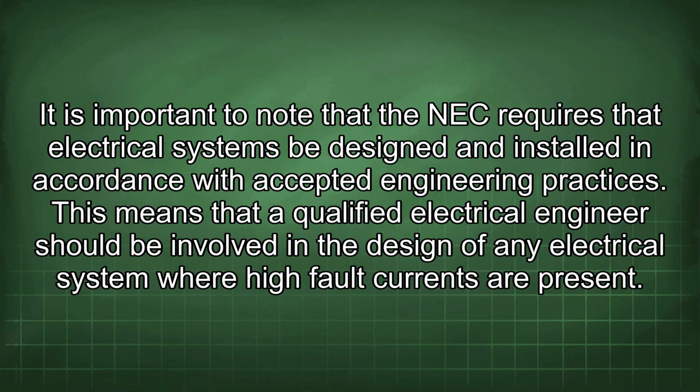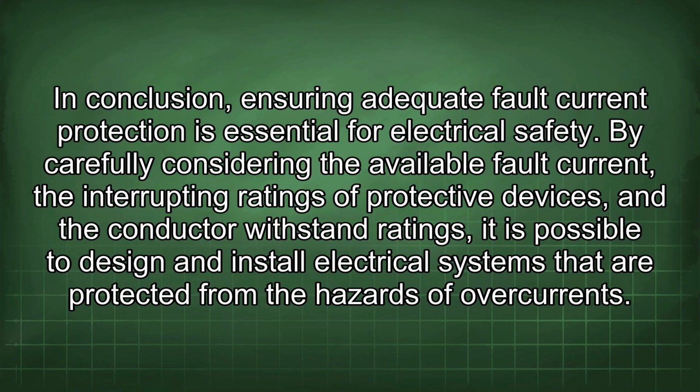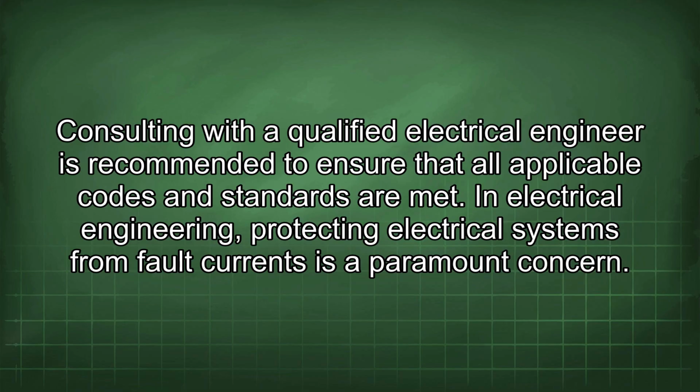It is important to note that the NEC requires that electrical systems be designed and installed in accordance with accepted engineering practices. This means that a qualified electrical engineer should be involved in the design of any electrical system where high fault currents are present. In conclusion, ensuring adequate fault current protection is essential for electrical safety. By carefully considering the available fault current, the interrupting ratings of protective devices, and the conductor withstand ratings, it is possible to design and install electrical systems that are protected from the hazards of overcurrents. Consulting with a qualified electrical engineer is recommended to ensure that all applicable codes and standards are met.